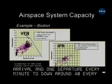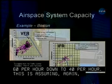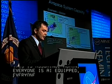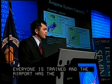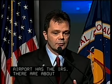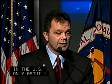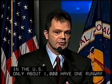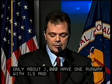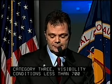And this is assuming, again, everyone's equipped, everyone's trained, and the airport has the ILS. There are about 5,000 airports in the U.S. Only about 1,000 have at least one runway that has ILS, and only about 100 will go down to what we call Category 3, which is visibility conditions less than 700 feet. So we definitely, a lot of airports have to close when we go to instrument conditions.